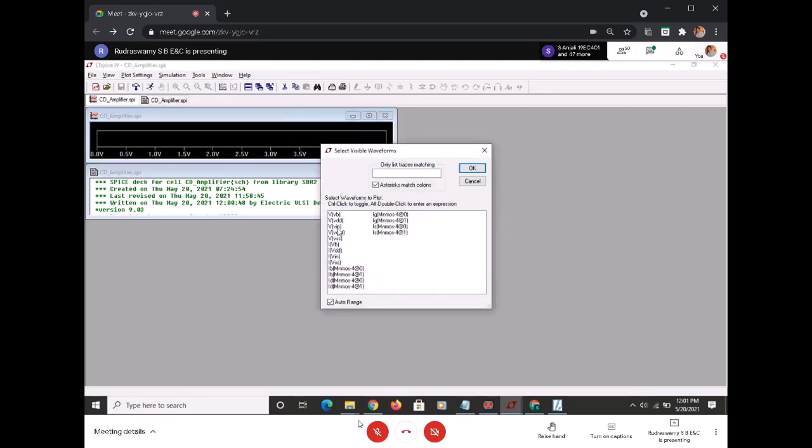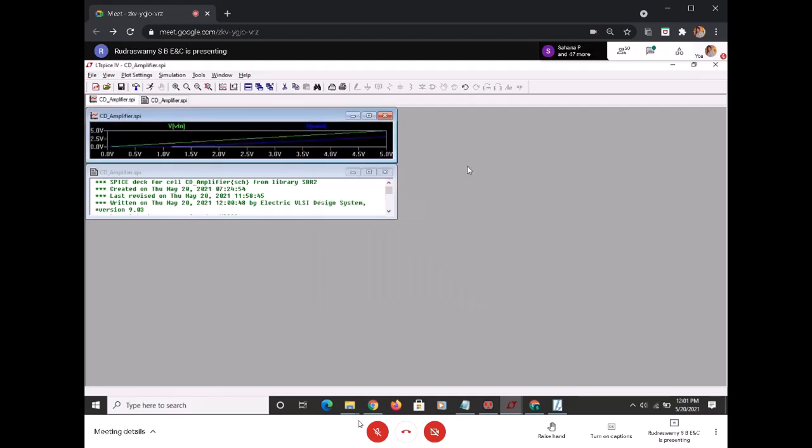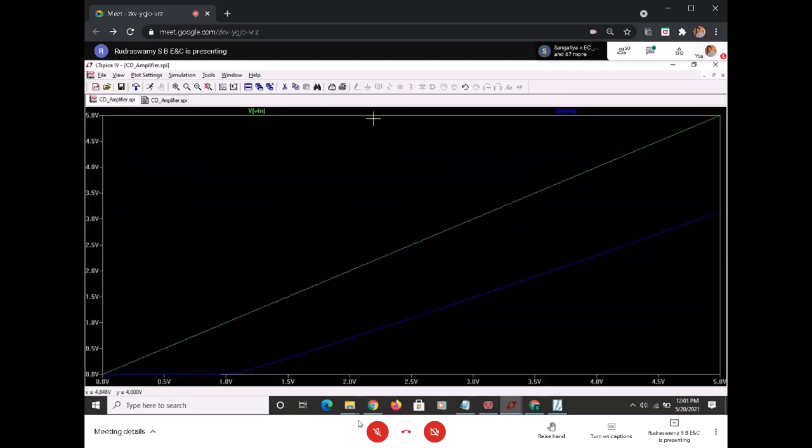So we have this trace here, V in and V out. You can see that this green is V in, which is ranging from 0 to 5 volts, and the blue one is V out. No doubt it is becoming linear. See, initially it is not. From 0 to 1 it is 0. Later it starts to increase, and where exactly it becomes linear is very important for us.